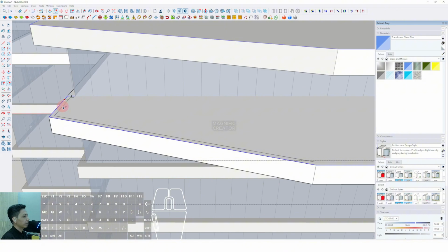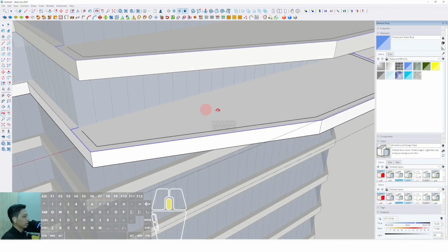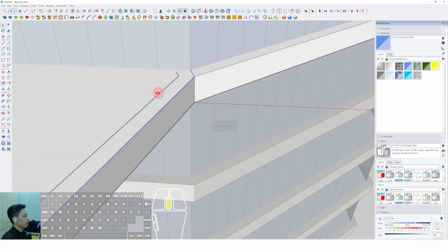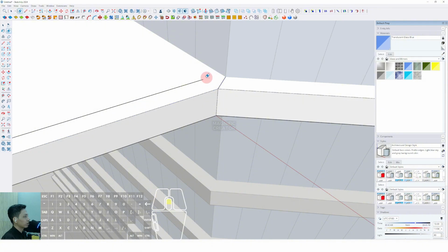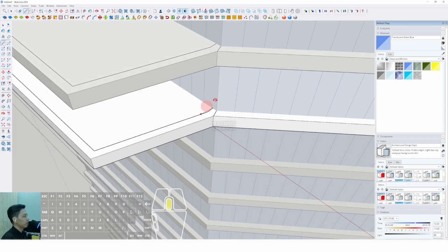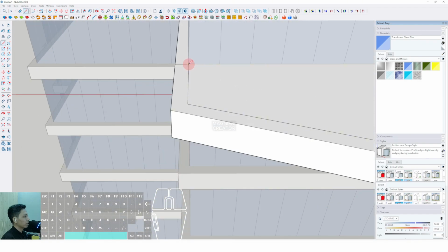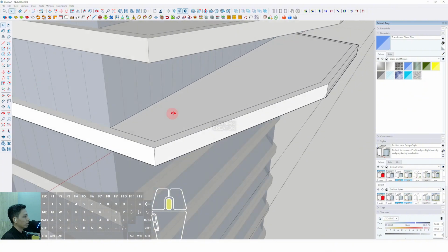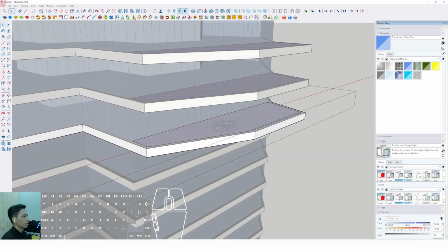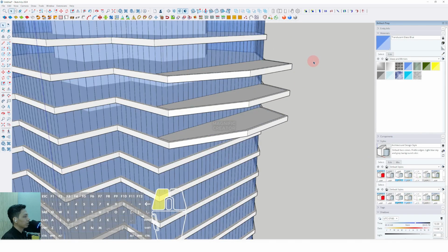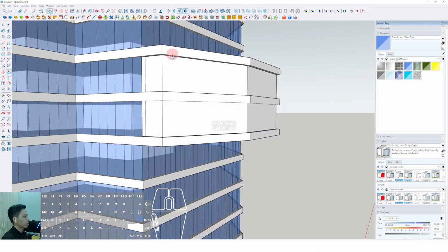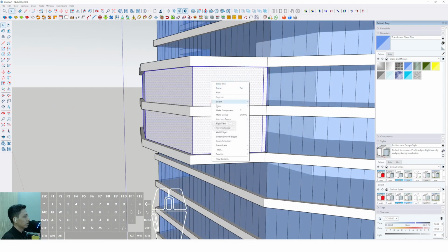Around 500 millimeter, and we can continue the line like this. Okay, we can erase this one. Then we can make it straight forward. Then we can connect this endpoint of the line until this line. Then we can erase some unnecessary or additional lines. Then we can click the surface and select edit, copy, extract from the group. Now we can select edit, paste in place, and we can push it up until this position. Then we can triple click, right click, make group.